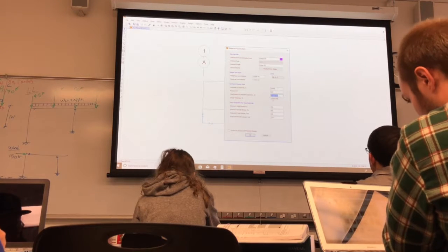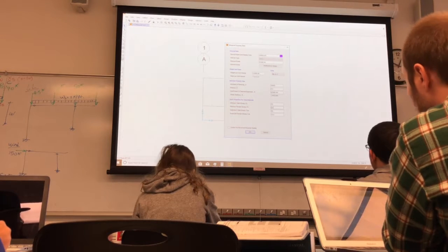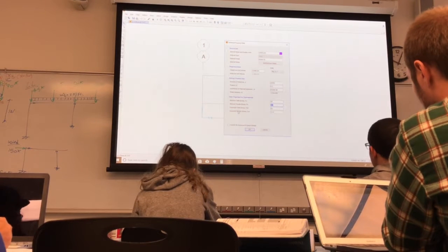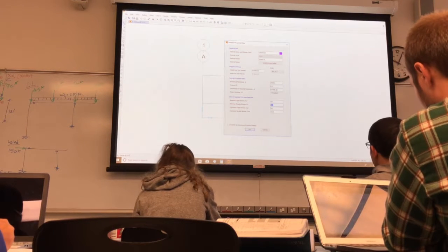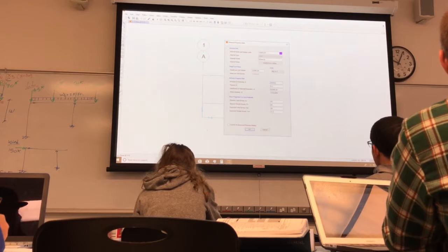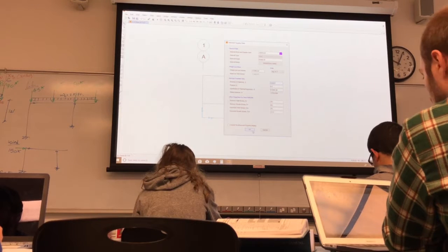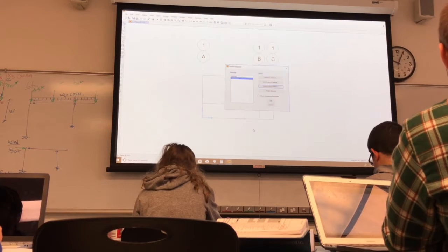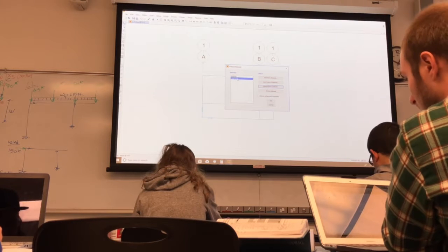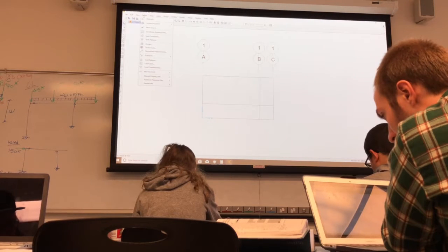We don't care about thermal. That's the shear modulus. We care more about the yield and ultimate. The expected stuff is for seismic, so we don't have to worry about it. So we care about the 50, 65, 29,000. Those are the most important parameters. It's already given, so I don't need to define a new material, because the material is already specified. I just need to check and make sure it's correct.